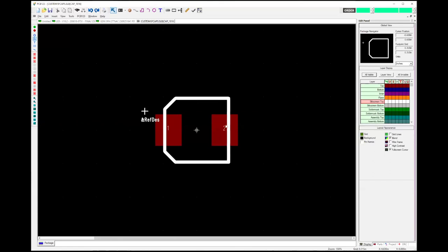And then what you would do is save it with the name. Right now it's just a capacitor 1816, but it's not anymore. It would be a capacitor something given by the manufacturer. The data sheet would tell you what size this is, or you would just give it the part number. It would be CRCW blah blah blah with a big long number afterwards to tell you that it's this specific part.